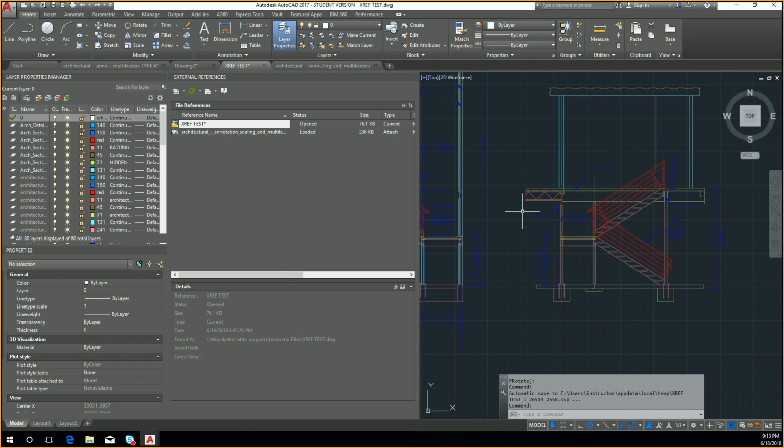Open up the block list. You can see it now. Let's go down to the bottom. There. Is that original? Is that the one you're inserting? You can purge all, you purge that one item, whatever you're trying to do with those. And now you should be able to detach.